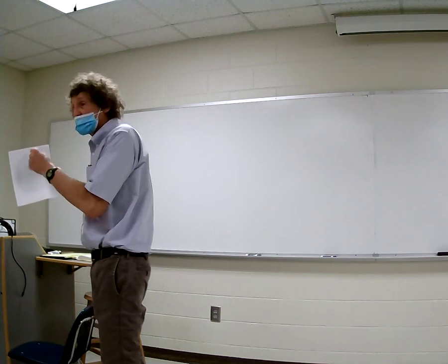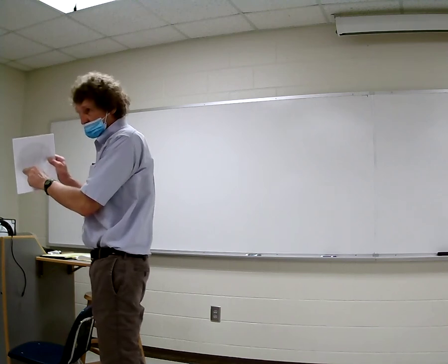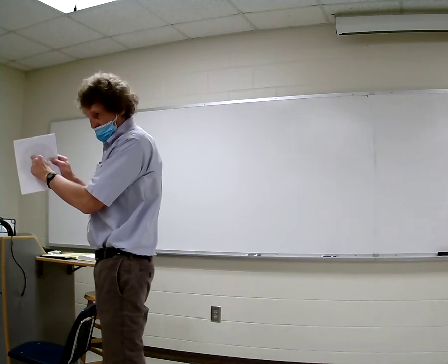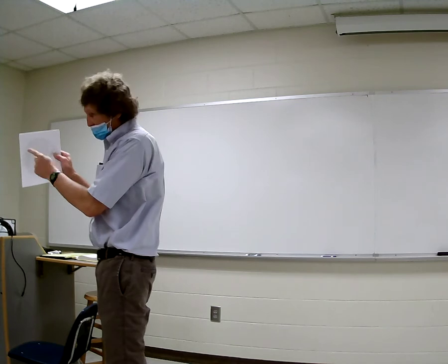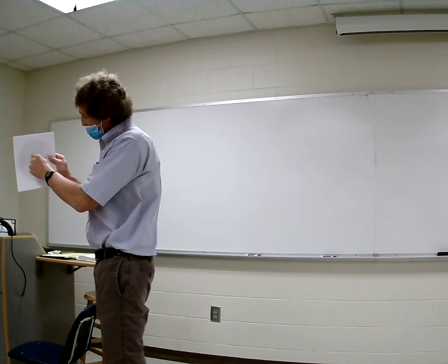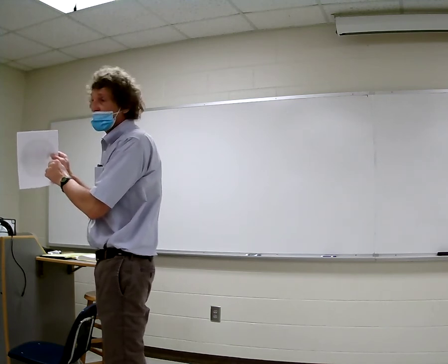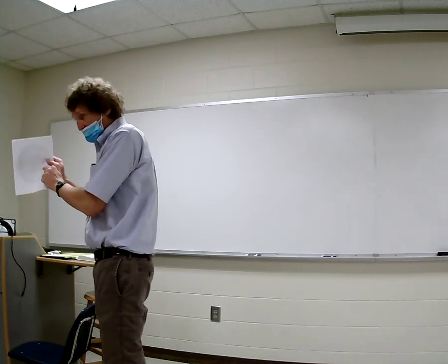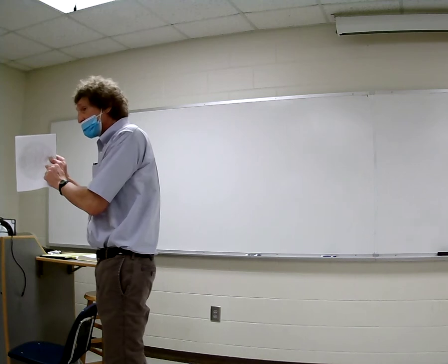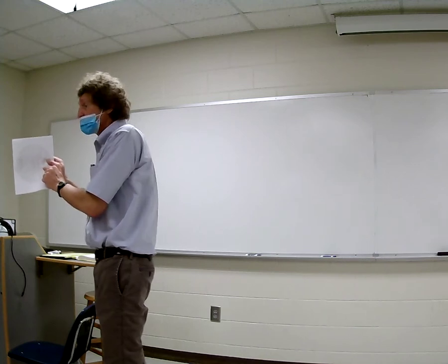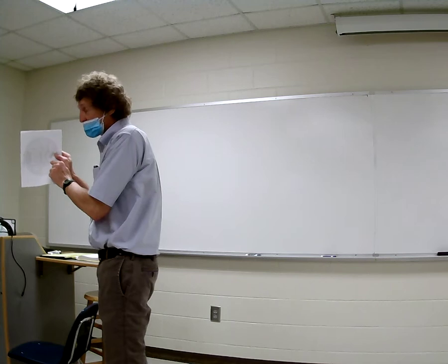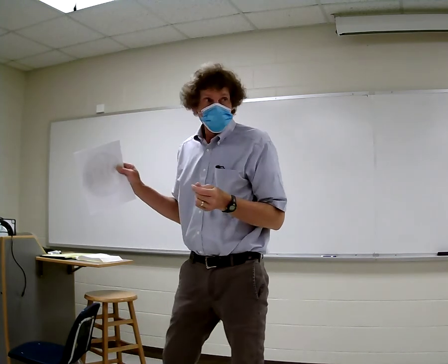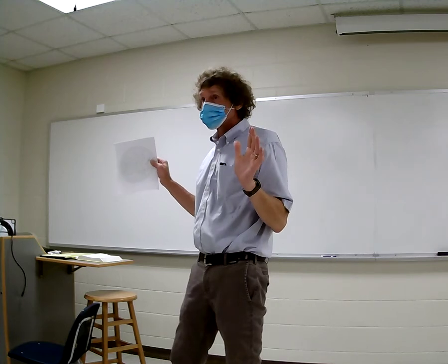Because now we're going to have plus J or minus J. This is an impedance, right? We have something inside here, so then we get to the rim. Take 1 over that. Remember, you're adding in series. Now you come over here, now you're in the admittance domain, right? It was impedance, now this rotated circle is the admittance. And there you find the value and you have to add whatever the J value is to get rid of it. So it's an admittance, right? And then the other way to do it, everybody with me on this? This is the standard stuff.